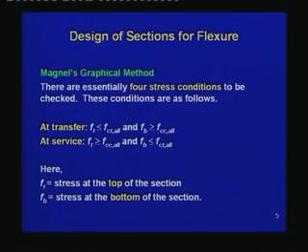At surface, the stress at the top should be less than the allowable compressive stress at surface. Now, if we write that in an algebraic equation, since both the quantities Ft and FCC allowable are negative for their compressive stresses, in that case, since the numerical value of Ft has to be small, the algebraic value of Ft will be greater than FCC allowable.